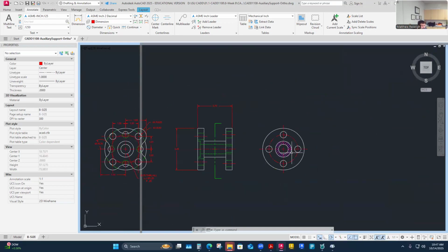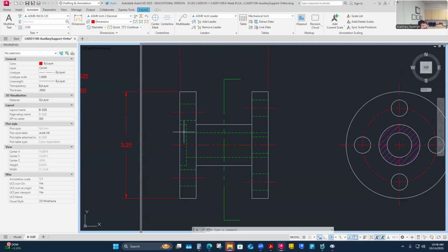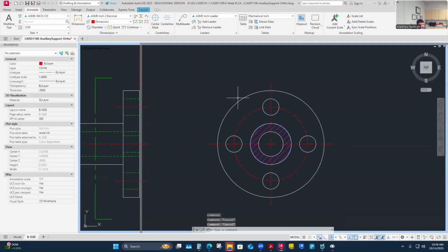But here's some stuff I haven't been able to call out. That's the counterbore and its features, so I feel like it won't be redundant to call this out here. It's the only place where I don't really get a rectangle. There could be an argument that the overall diameter is not the best to dimension right here for this. Let me focus on the outer plate first.